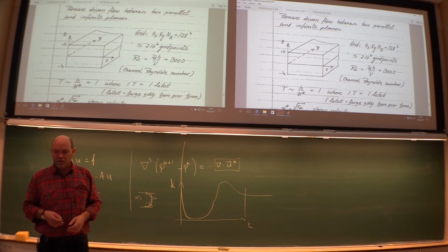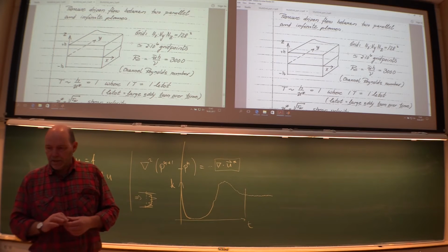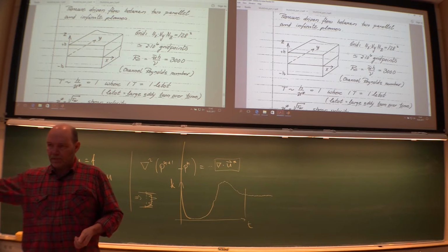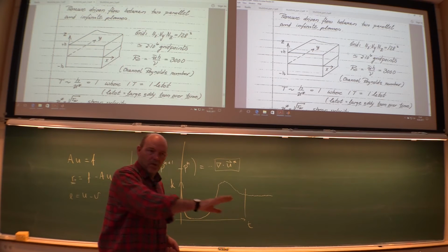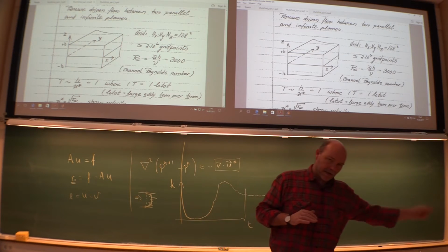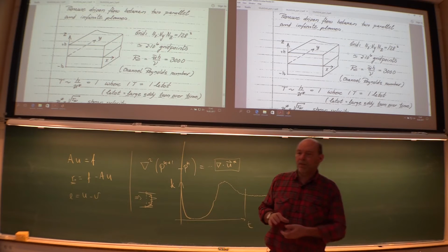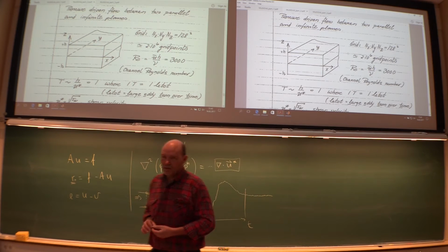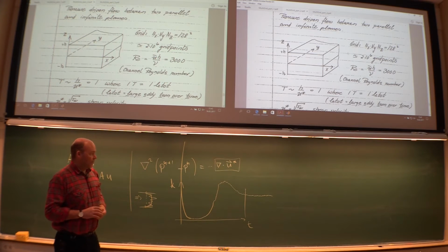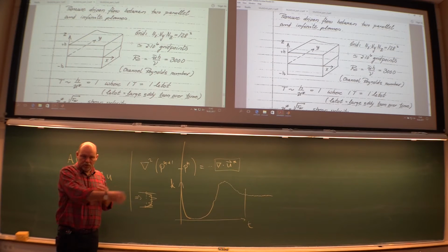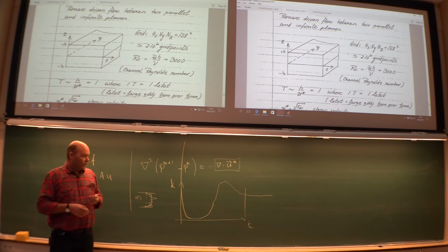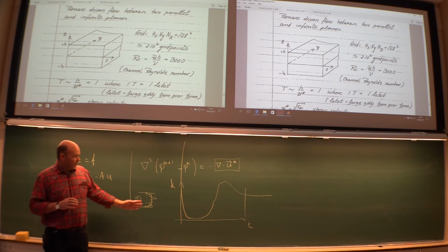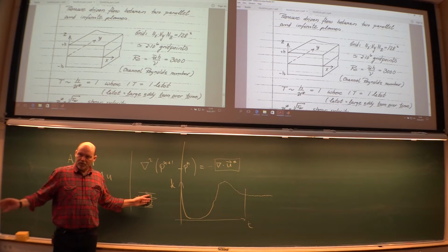So in a wind tunnel, you can drop a feather at the inlet, let the feather follow the turbulent flow, and then determine exactly where that feather is going to end up on the other end. No way. You can't do it. You need millions of time steps, and you're going to accumulate errors anyway. So the way you should think of a DNS: produce a whole bunch of different solutions of the Navier-Stokes, and then you make an average.